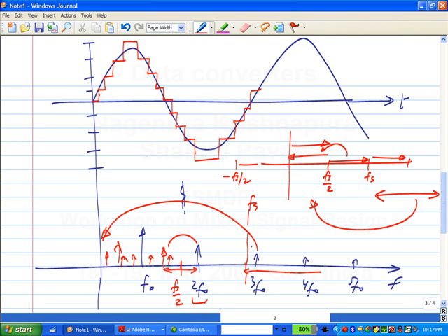Now, this is sampled, right? So that means we are only interested in the segment between 0 and Fs by 2. Okay, this much. So what will the spectrum between 0 and Fs by 2 look like? So, alias distortion. We have F0, the main signal that we always had, and then all the distortion components get folded back into 0 to Fs by 2, right? So you'll have a lot of tones, infinite number of tones really. Now depending on the frequencies and the relationship, you may be able to distinguish them as tones. It may smear out as noise. So that is what quantization noise is. It is just alias harmonic distortion.